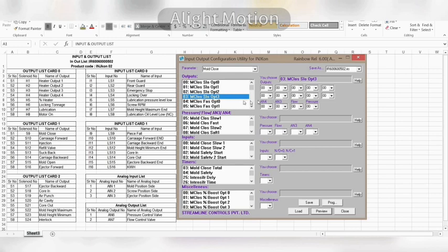Whenever a boost parameter is on in your PLC, that option's output will be on in the program. Such as, if boost 0 is selected in PLC, the output defined in option 0 in your program will be on. If boost 1 is selected in PLC, the output defined in option 1 in your program will be on. For 4 such boosts, 4 options are given.